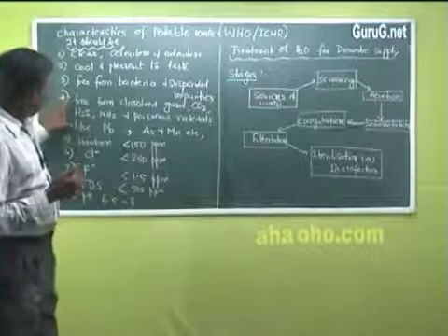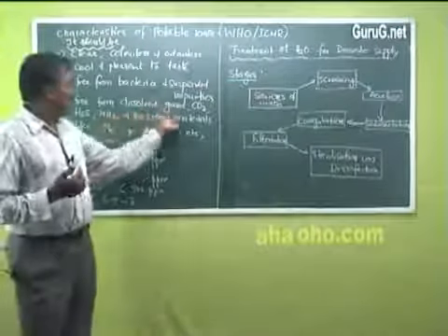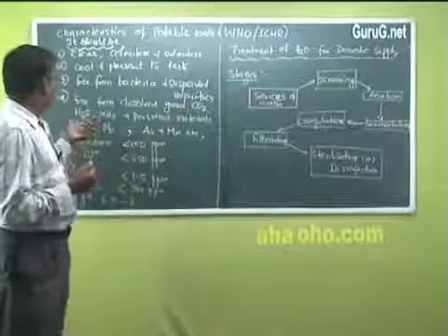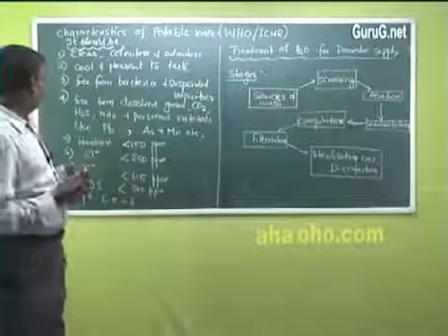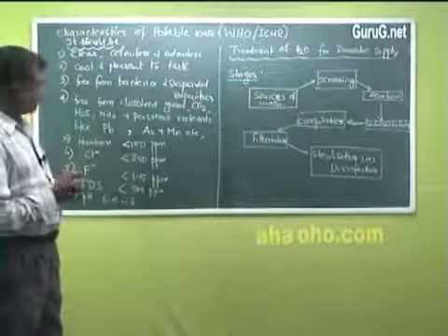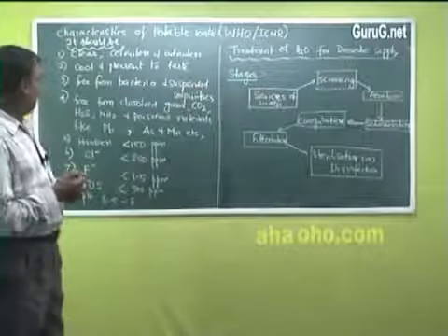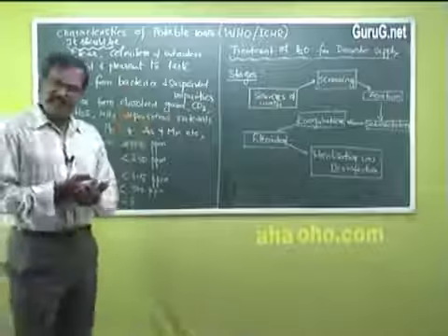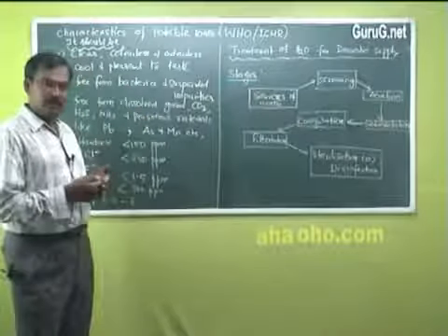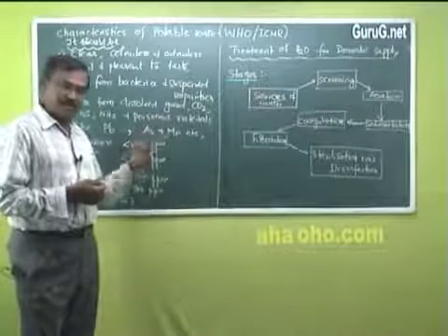And it should be free from dissolved gases like carbon dioxide, which will make the water acidic, and hydrogen sulfide will give bad smell, and ammonia also, and some poisonous materials like lead, arsenic, manganese, and so on.